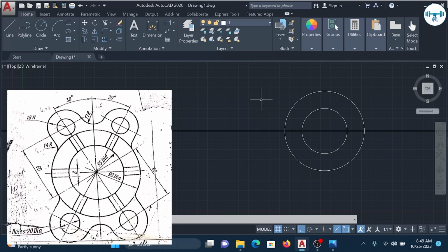We look at those lines carefully. We can see that these two lines are 8 mm apart. Can you see that? So check your drawing, the left part of these circles, you see where the dimension is. The lines are 8 mm apart. So if it's 8 mm apart, and we have put the horizontal construction line, which means that this line is 4 mm. The first one is 4 mm above this construction line, the other one is 4 mm below it, making up the 8 mm. So I'm going to come and pick my what, line 2.